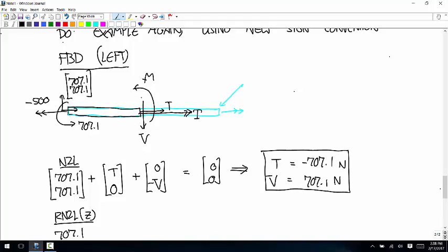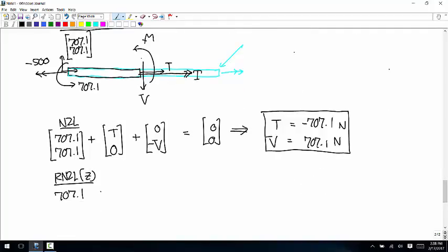So for that one, we just add on M. And then are there any other forces? Those are both couples, so we didn't have to choose an about point yet, but now we're going to have to. I'm going to put my about point there at the left end. Are there any other forces applied to this member that create a moment about that left end point?